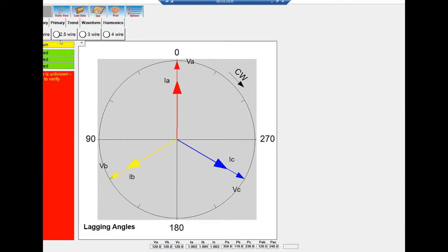So for this demonstration, I'm generating a perfect sine wave, 3-phase, 20 amps into a primary to 105 CTs, feeding that with 120 volts across all 3 phases. With that being said, that'll give you a little bit more lead into what I'm about to discuss and what you'll be seeing here. And then I'll throw in some harmonic content later to show off what harmonics will look like as well and to mix things up a little bit so it's not perfect.